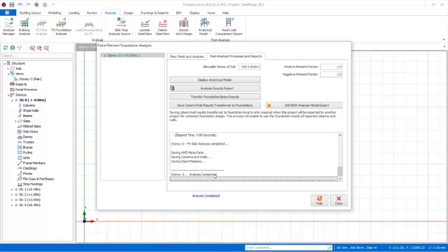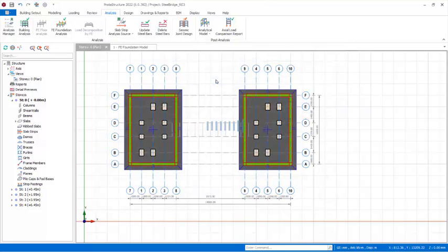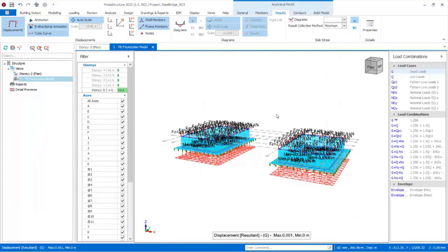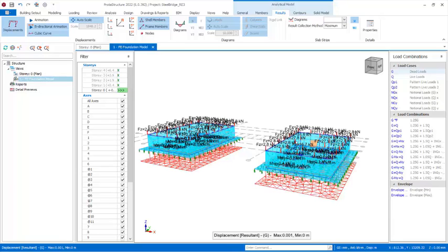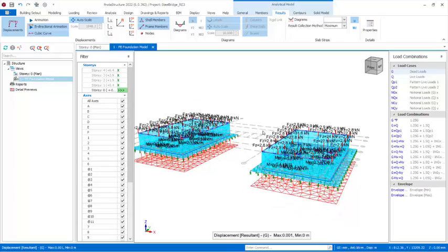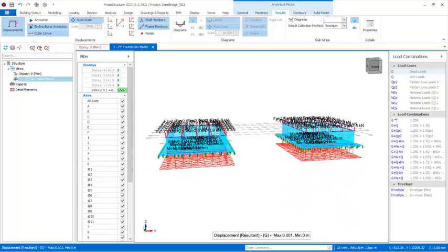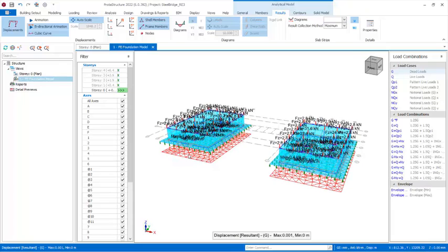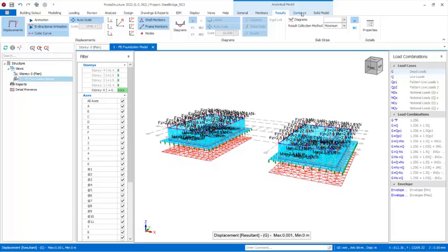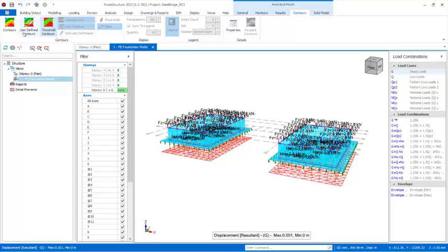So you can see over here, what you need to do is design the moment and the displacement, as well as design and provide the area of steel successfully. To do that, you have to click on the display analytical model option. Having clicked on this option, you have this. Once you have this, you can see now this is the foundation of this structure. We want to be designing this. For us to do that, you go over to the contour tab right there. Click on that tab, and then you have this contour.